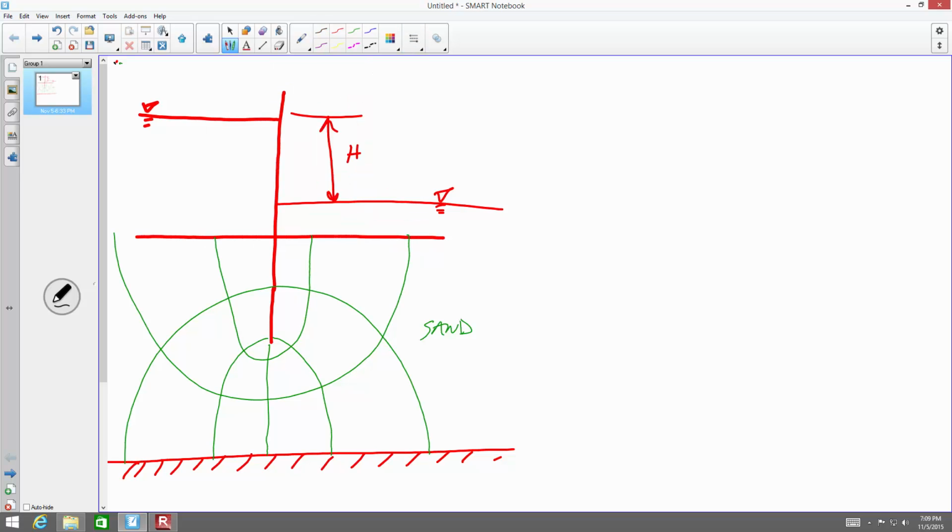And the sheet pile is driven in a shallow lake. The area on one side is to be pumped down as shown. The foundation is sand underlain by impervious rock. A flow net has been drawn as shown. H equals 5 feet. K for the sand is 0.2 feet per minute. What is the flow per lineal foot of sheet pile?